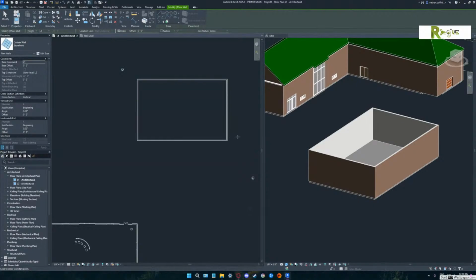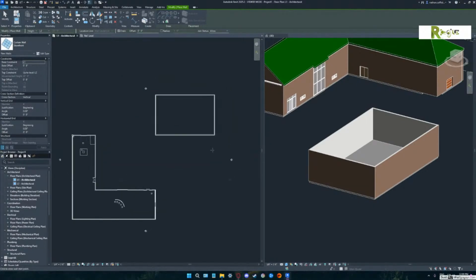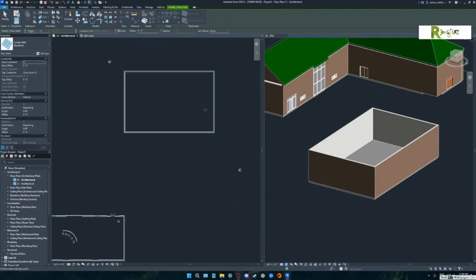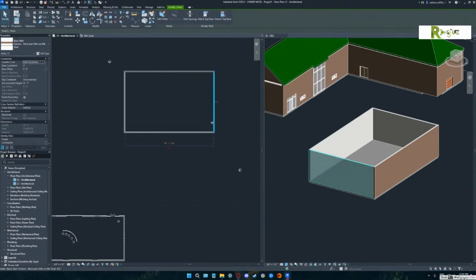So if you picked on one of those walls, escape 2 times, you're in draw something. Pick that wall. Now use your left arrow or your right arrow. You see how you can sort of work it, right? And what happens is hold your shift button, and then hit the arrow, and you'll see it's a big jump.